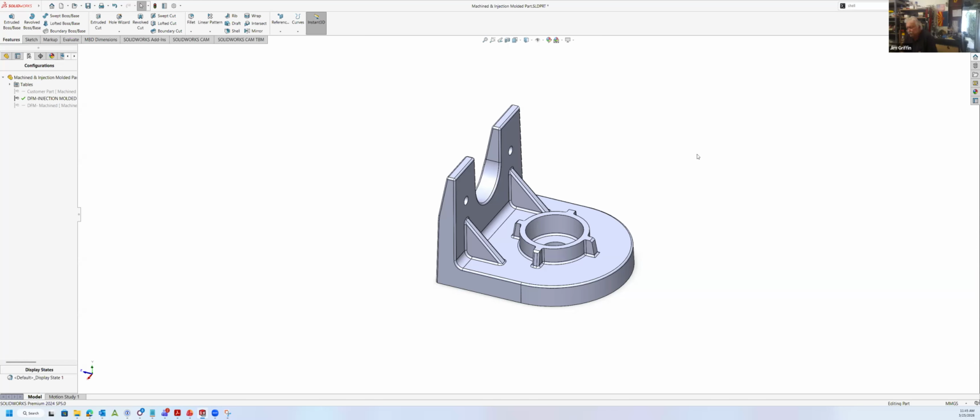When you leave it like this, you can also do a honeycomb mesh on the inside, which will help reduce the material without drastically reducing the strength. The other thing to keep in mind, going back to the very first slide when you were collaborating with the machinist, the people buying the material really need to get with the machinist and find out how they're planning on holding something to machine it so that you make sure.